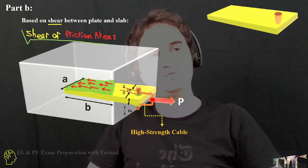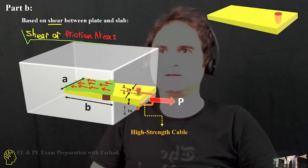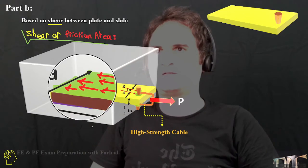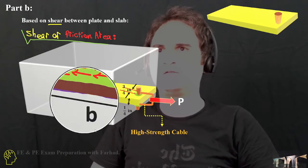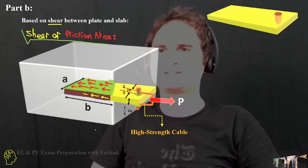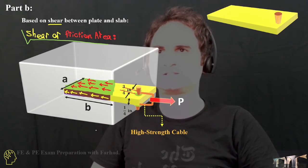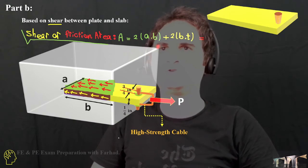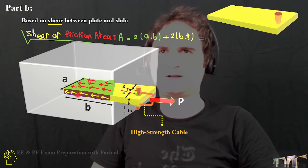At the same time, we have two shearing areas at the sides: one at the top and one below, each of area A times B, and two at the sides, each of area B times the thickness of the steel, T. So the frictional area is 2AB, the greenish area, plus 2BT, which is the part at the sides.